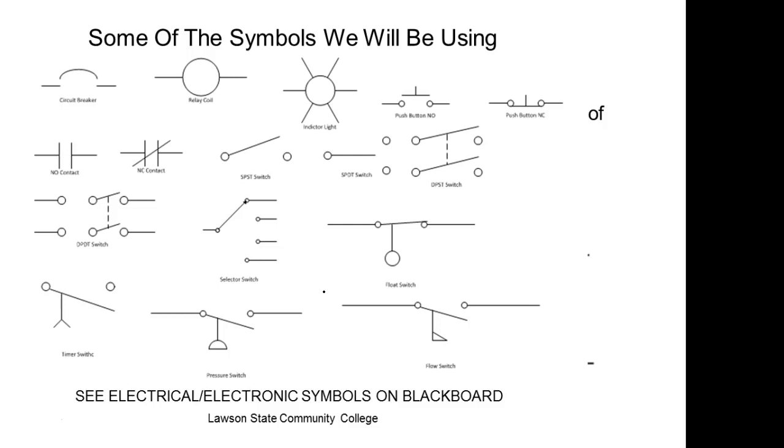Float switch. Y'all understand what a float switch is, right? If you've got a house with a basement, it might have a sump pump in there. It doesn't run all the time. When does it run? When you get water in the sump, right? So when the water comes up, on this one, this would be normally closed, so this one will run all the time, right? So we have to have it normally open.